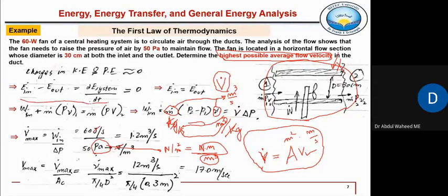equation. So whenever you write the equation, again you have to be careful about the units. Is it E dot or only E or small e, right? So in this question, because 60 watts was given, because it is a flow, it means m dot, everything is changing with respect to time. Not changing, constant, but with respect to time there are 60 joules which are entering. There is a certain mass which is flowing with respect to time. So that's why everything was dot. In the previous question, it was without dot, right? So these are the things which you have to be careful about.